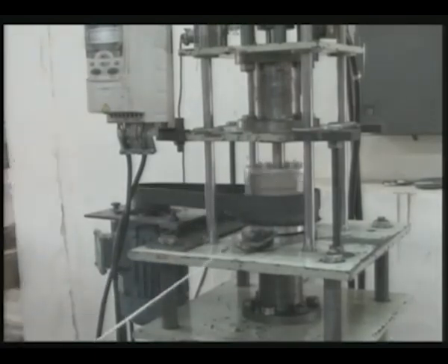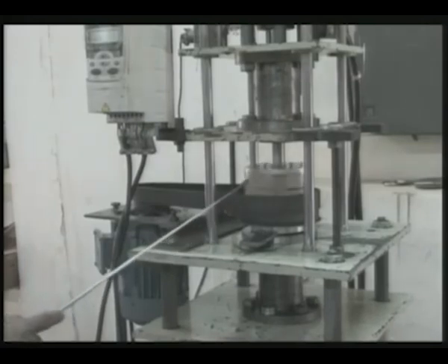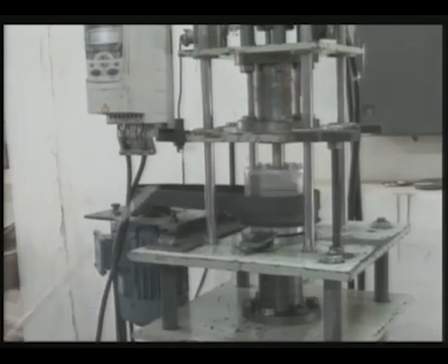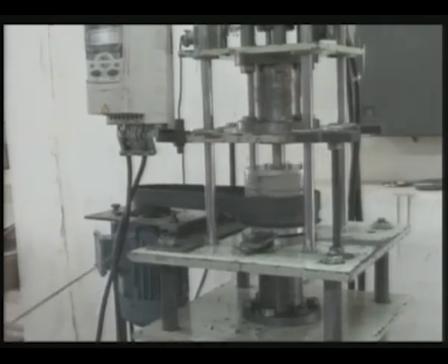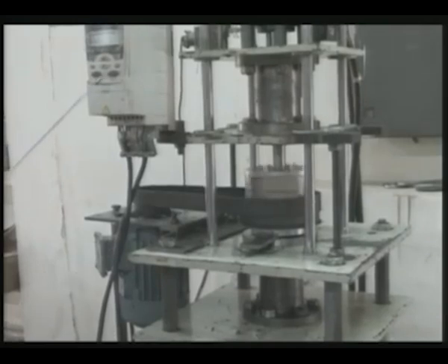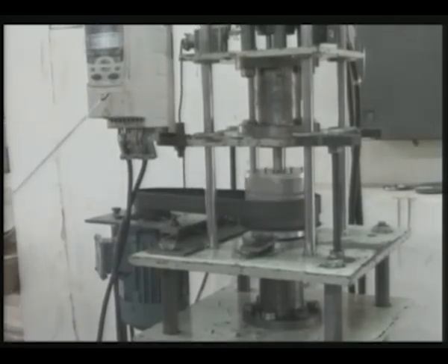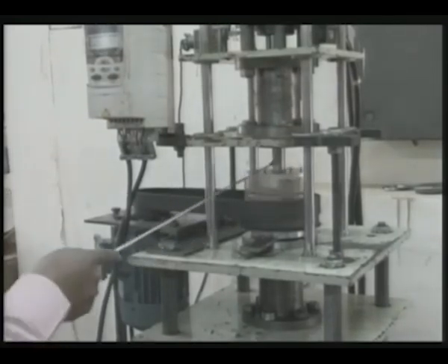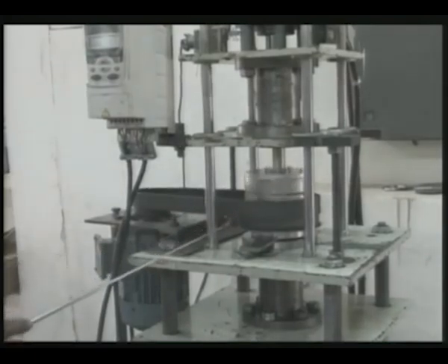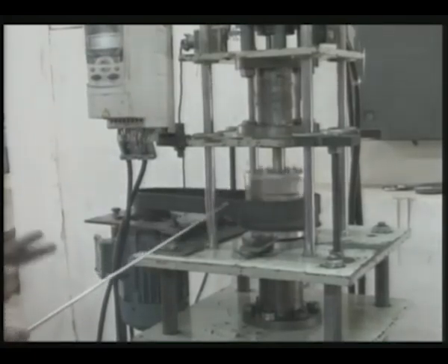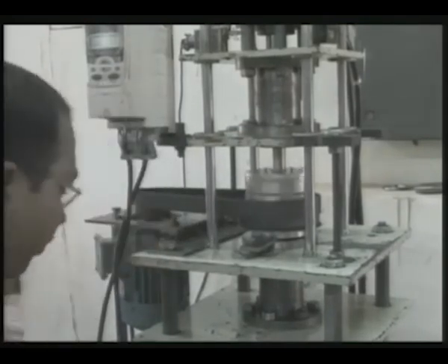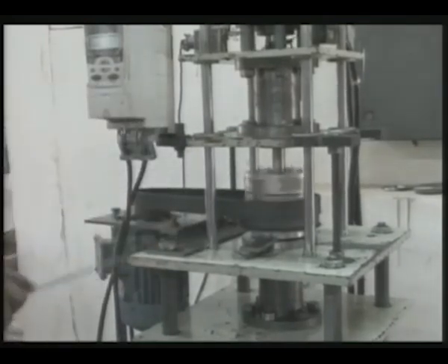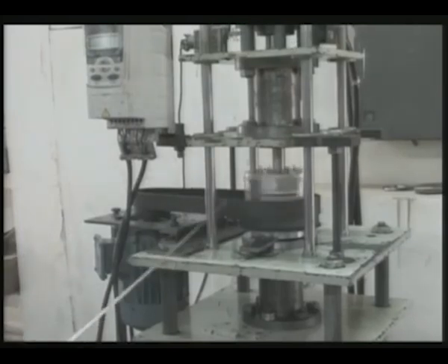In the RMFF process, this magnetic field is rotated via a permanent magnet, and this rotation is provided by an AC synchronous motor, and the rotational speed of this motor is controlled via a variable frequency drive. The accuracy of this drive is 2 RPM. See how these permanent magnets are rotated through a fixture, and inside this workpiece fixture the polishing media is given reciprocating motion. So there are 2 motions. One is this reciprocating motion and another is the rotational motion.